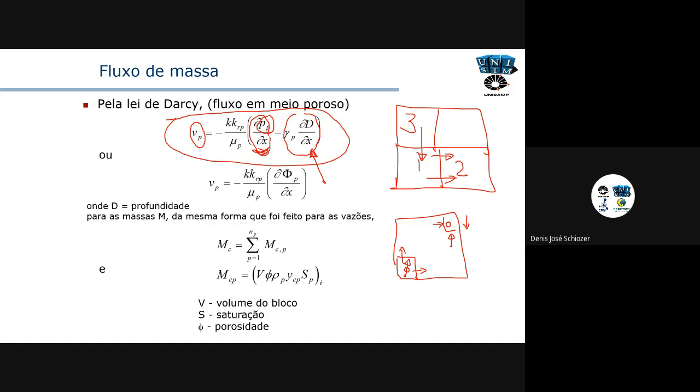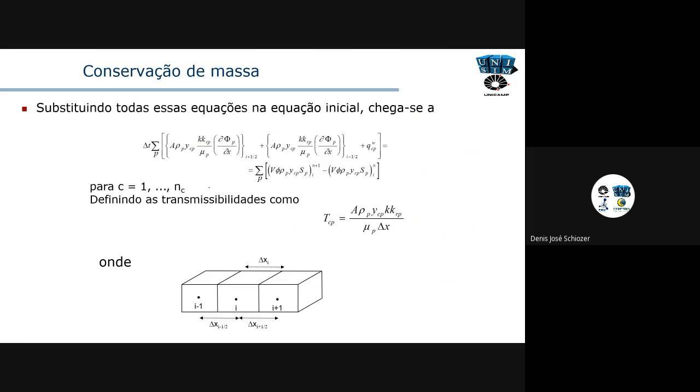So if I have different pressures for the water phase and the oil phase, this is also part of the physical explanation for why the fluid is moving from one block to another, okay? So it's moving because of a difference in pressure. It can be absolute pressure or capillary pressure, and also gravity, okay?